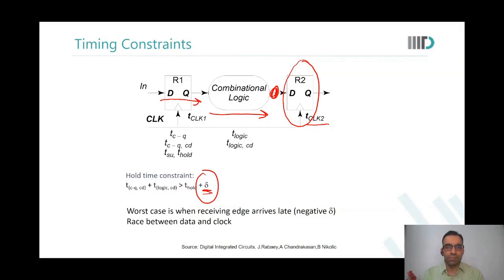So when we are considering the setup time constraint, we are considering two clock edges which are T period apart. But in the hold time, we are considering the same clock edges. Yes, hold time is always with the same clock edge. Sir, so what does hold time mean? Let us understand that. Hold time says that when my clock edge comes, the transitions from the previous flop should not have reached me yet until after the T hold period.